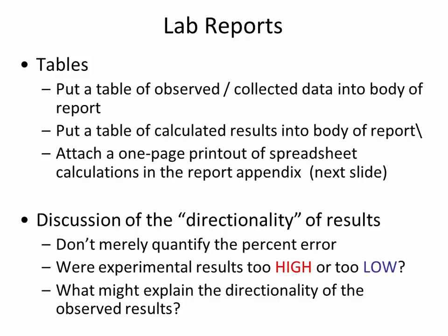Now you already know how to calculate flow rate based on the experiments we've done so far, but if you'll notice below the table I explain what's in every column, I guess except for run. I didn't explain that, but that's obvious enough. So you'll notice volume. It explains all those values, what it comes from. And so volume is measured by watching the water level rise up on the glass tube when the plug was inserted into the drain. So I explain how that volume column was developed. And then time of collection, measured with a stopwatch, quantifying the time that has passed as the water level rose between 2 volume marking points.